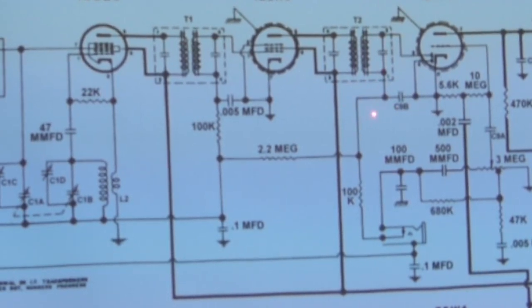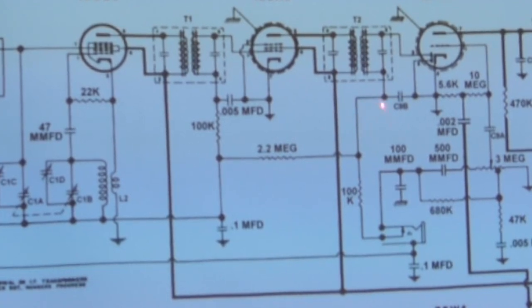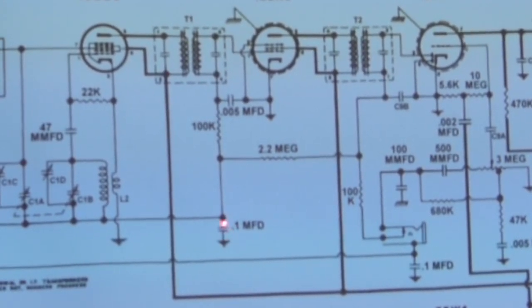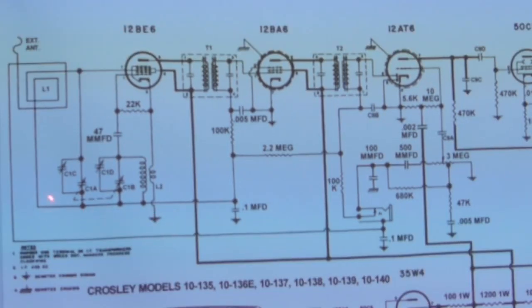So, all right, we come down here. We've got rid of our 455 kilohertz carrier there, or pardon me, it is a 455 kilohertz carrier at that point. And you come down here. Here's the AVC split off. So you'll notice there's a very high meg, a very high value resistor here, and quite a hefty capacitor down there. What that does is it filters out the audio portion, and you're left only with a varying DC portion. The purpose of that is to provide a negative bias, and you follow this line over through the loop into the grid, the signal conducting grid of the input tube.